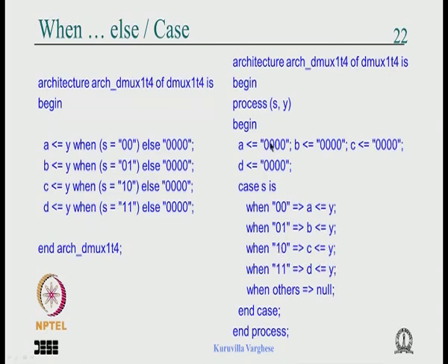Say A was assigned 0 at the beginning, and the event happens at 100 nanoseconds, A was assigned at 100 plus delta, but when it comes here A is reassigned with Y, so that is replaced with the Y, so there is no issue.